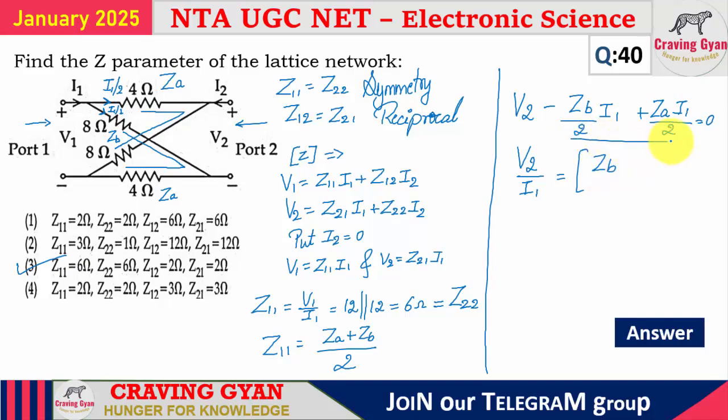If I'm sending these two terms to the other side, what am I going to get? (ZB minus ZA) whole divided by 2. That's it. So V2 divided by I1 is what? Z21, which is the same as Z12. What is the value of ZB? 8. What is the value of ZA? 4. 4 divided by 2 is how much? 2 only.